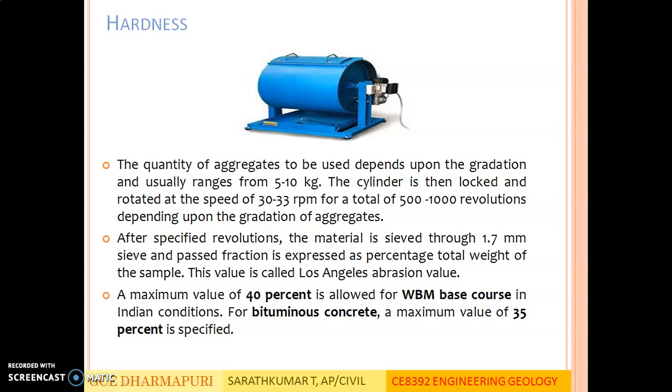If the percentage of fines is lesser, the rock has higher hardness. A maximum value of 40% is allowed for water bound macadam base course in Indian conditions. For bituminous concrete, a maximum value of 35% of fines is specified.